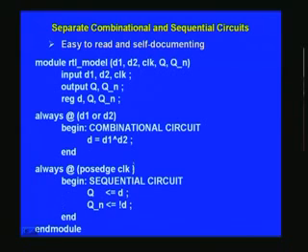And for simplicity, I have omitted the negative edge of reset, which we had considered earlier. And once again, you have a begin and end. Note that just as we identified this block as a combinational circuit, we can identify this block as a sequential circuit. Here, whatever is the data input, we merely have to register when the positive edge of the clock occurs. And this also we have seen earlier. And this is nothing but an inversion of D.